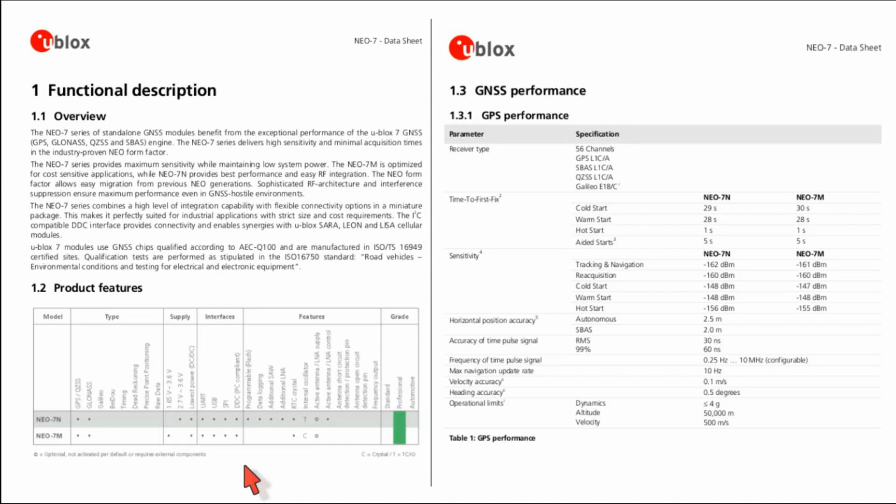The 7N also has an internal temperature control crystal oscillator, which not only speeds up the synchronization with the satellites, but can produce reasonably stable PPS frequencies without satellite reception. On the other page, note that a 7N allows the selection of the time pulse signal frequency up to 10 MHz.